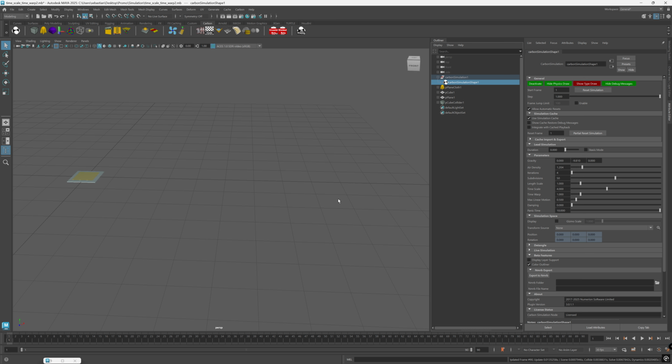Now this covers timescale. What about time warp? Time warp is a multiplier of the time step, and it changes the meaning of the elapsed time by contraction or dilation, while timescale is a ratio which defines the value of the time on the scene. So in practice, what is the difference? The difference is you should not animate your timescale, but time warp should be used when you go in and